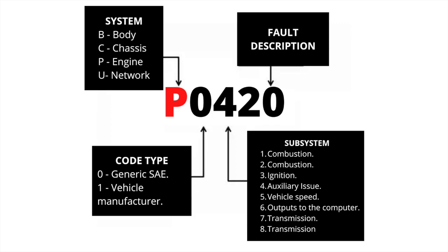For powertrain codes, example, P2000. A number 2 will always refer to generic codes. A number 3 will refer to a manufacturer's code if it is less than P33, P30 to P33, and to generic codes if it is between P34 and P39. As for the other systems such as chassis, body, and network, number 2 will always be a manufacturer code and number 3 a generic code.